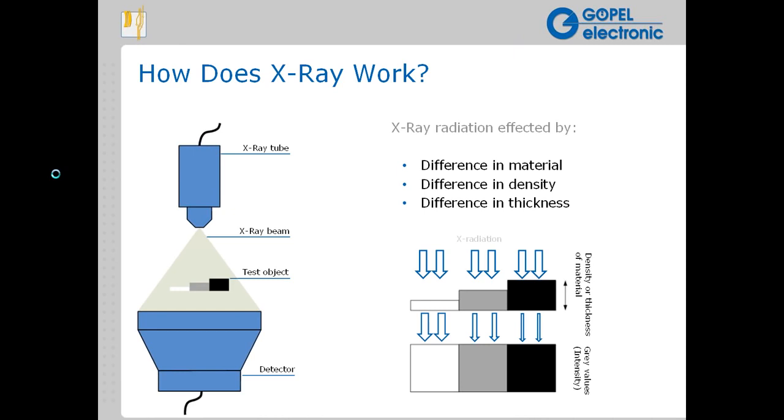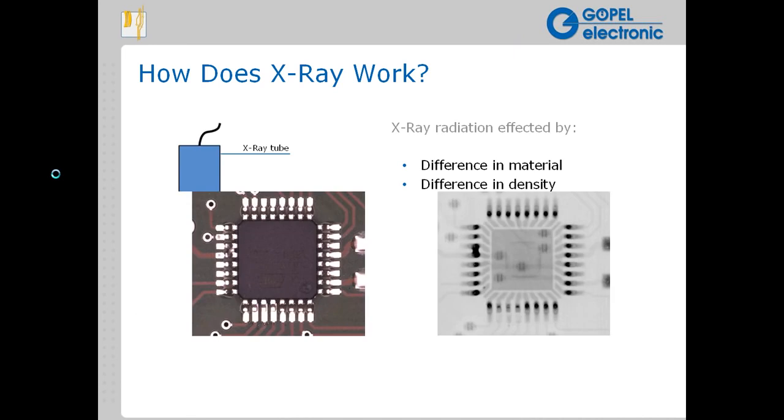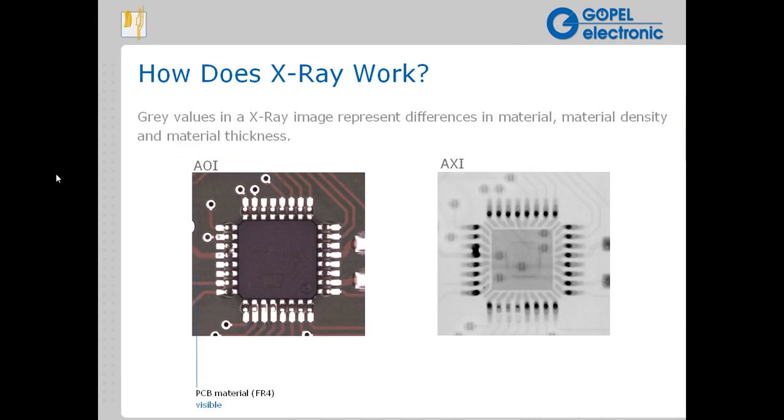The IC pins are a little bit more dense, and they're also metallic, so we get a middle density interpretation from those. As you can see, the gray is slightly darker, and you can contrast it against the background of the PCB board material itself. The plastic case is very visible in optical, of course, but not very visible at all in X-ray. It again is a low density material, so you can see components on the other side of the board in this particular case right through it.